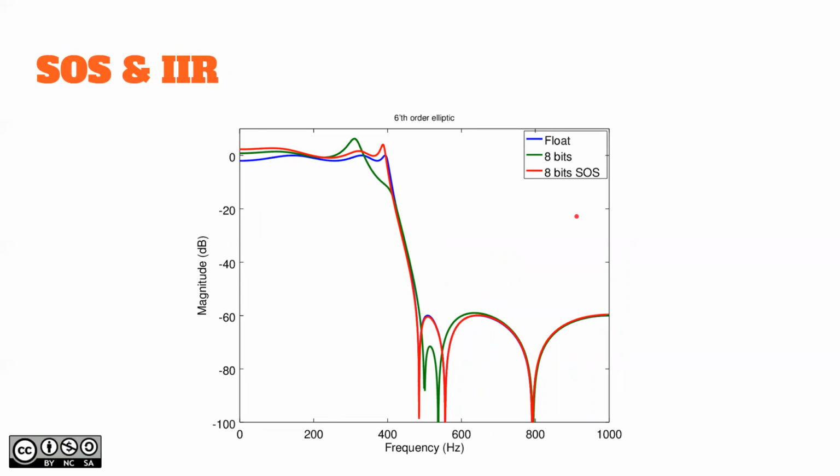On IIR, usually the stop band is okay-ish because these poles are dominating the amplitude response. They bring extra gain. So if you have a small increase or decrease in attenuation, usually it's less than what the gain does.